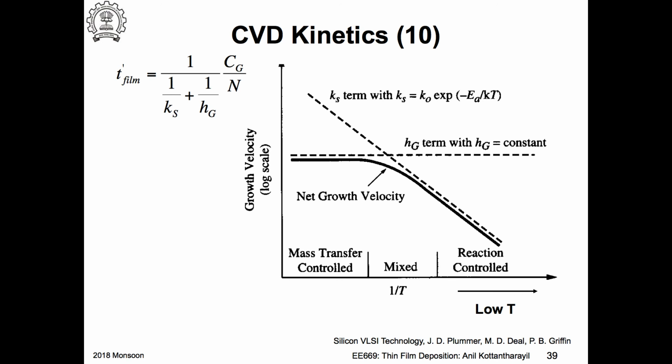That is why, if you remember, going back to the discussions, some of these processes like epitaxial growth of silicon need high temperature. If I want to epitaxially grow a thick film of silicon, the temperature has to be high, and then I am worrying about how to design my process chamber so that the mass flow is uniform.